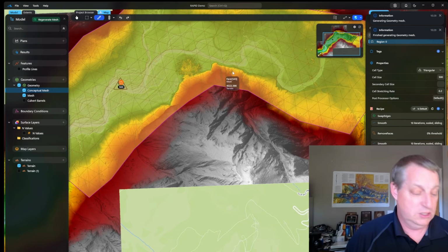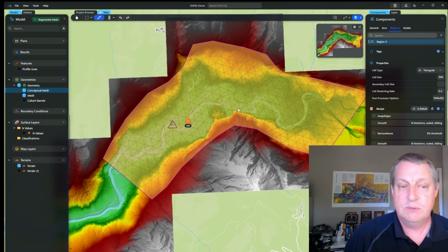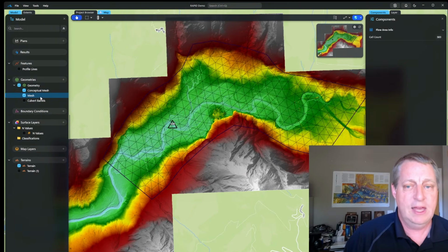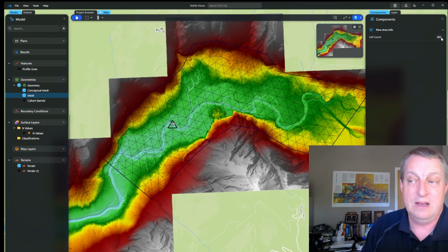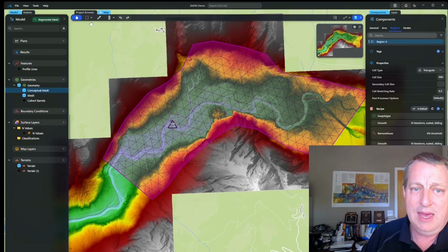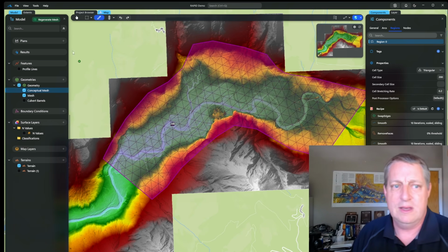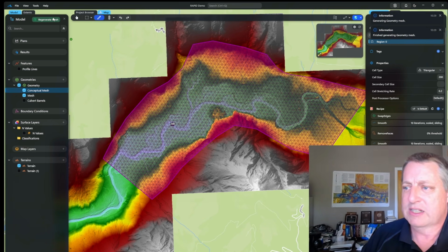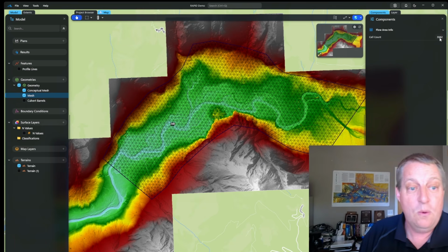Let's generate the mesh. I really like that mesh for a first cut expedited analysis, but we can go in and now click on the mesh and see that's less than 600 cells. That's not going to kill our runtime. And so what if we go in and say, actually, I'm trying to make the simplest model I can, but we can definitely get away with 200 even with a simplified model. And we regenerate cells. That'll give us about 3,500 cells. Well, that's pretty good. Let's do that. Okay, so we have our geometry.